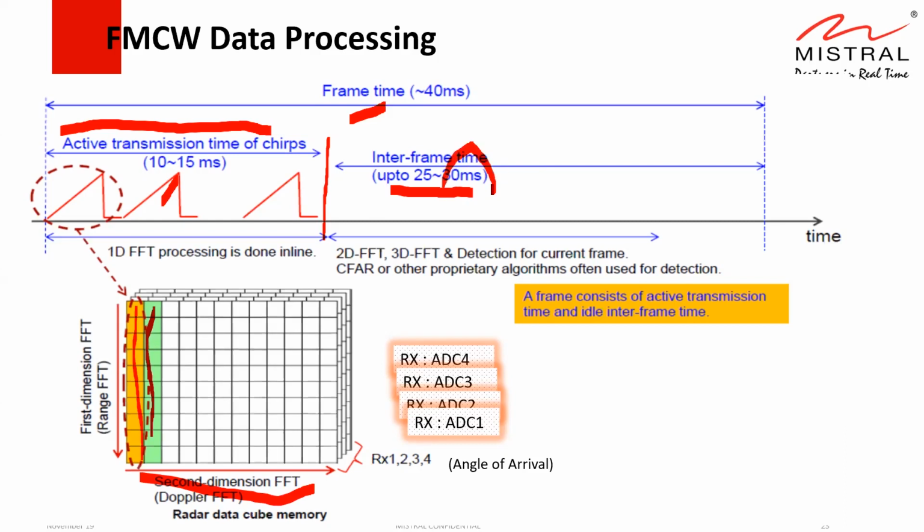During this delay time, you perform the Doppler shift, the angle of arrival, angular velocity, and any other functions like CFAR or log magnitude computations. So by the end of the frame, the complete processing should be done within the chipset itself.